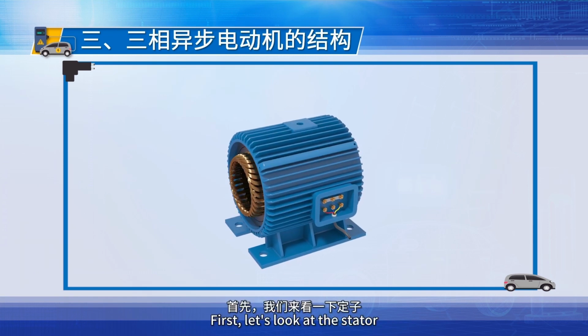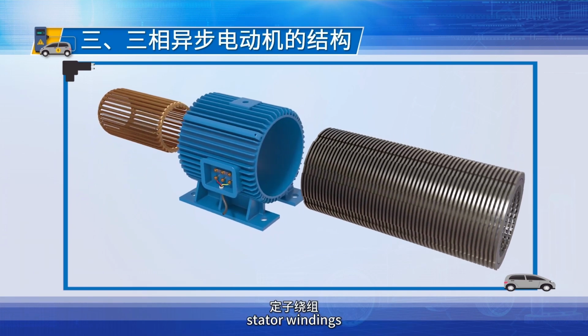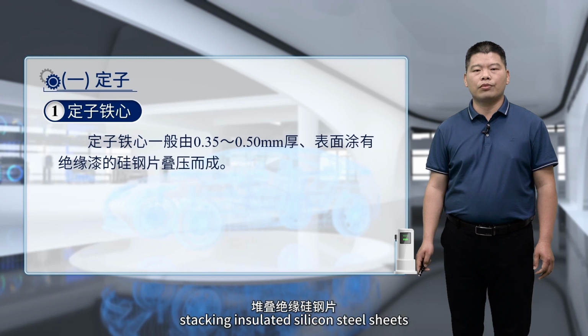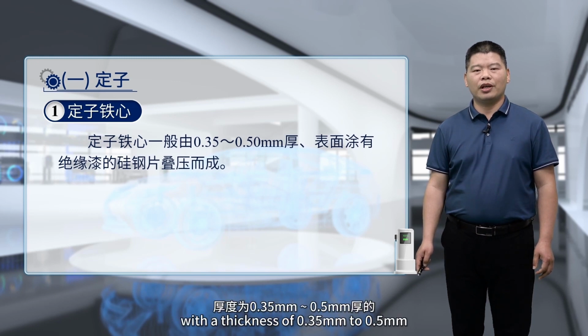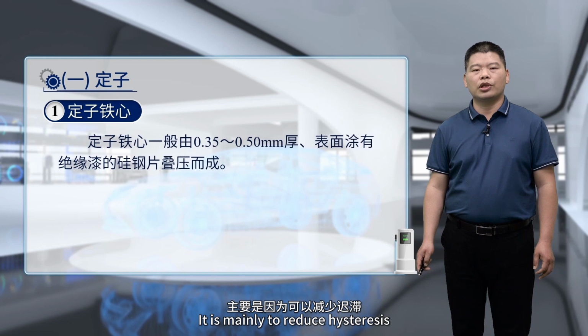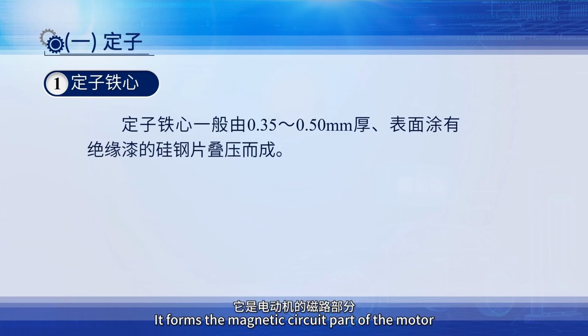First, let's look at the stator, which is mainly composed of a stator core, stator windings, and a motor frame. The stator core is typically made by stacking insulated silicon steel sheets with a thickness of 0.35 mm to 0.5 mm. Why is it stacked? It is mainly to reduce hysteresis and eddy current losses. It forms the magnetic circuit part of the motor.